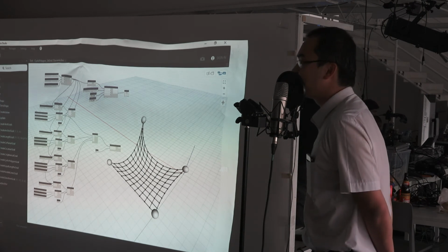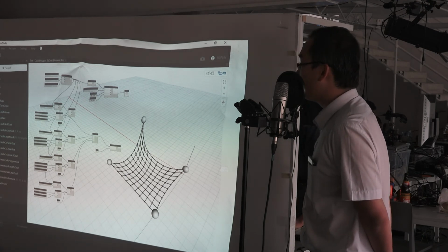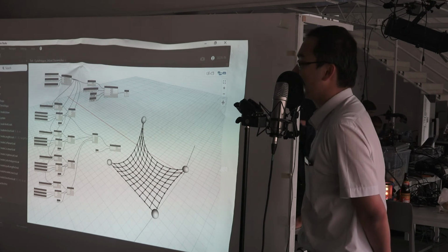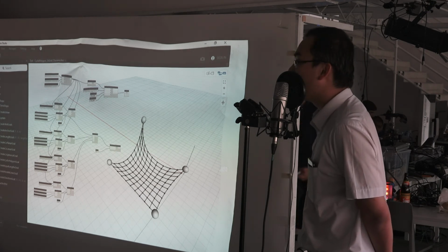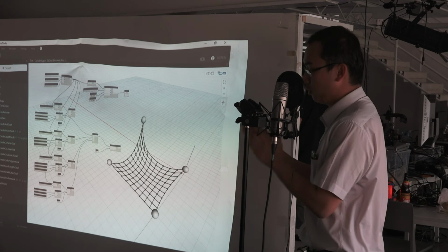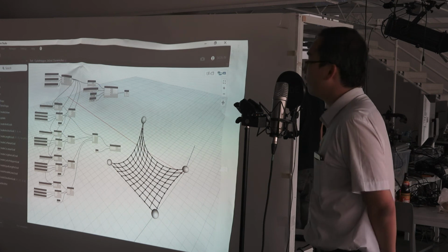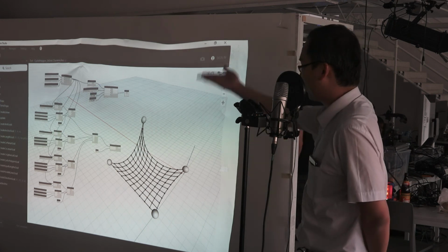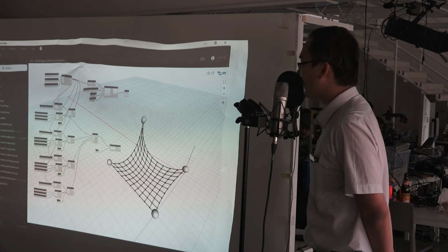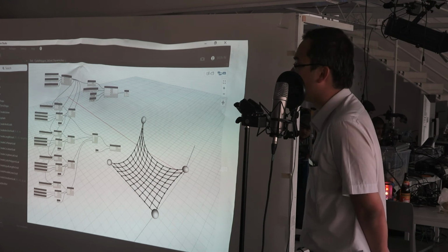Okay, thank you. So how does this differ from the PQ mesh ideas that have been floated around, like the Evolute tools and others that try to maintain planarity in quad meshes? This is more than just a planarization goal. You can have a goal to keep lines parallel, or a goal that maintains angles. For manufacturing, for example, you don't want the panels or the quads to form a small angle. So it's up to the designer and also me to define this custom constraint library. And it works iteratively. I'm not sure if Evolute is iterative or more of an analytical solution where it snaps to the solution right away.